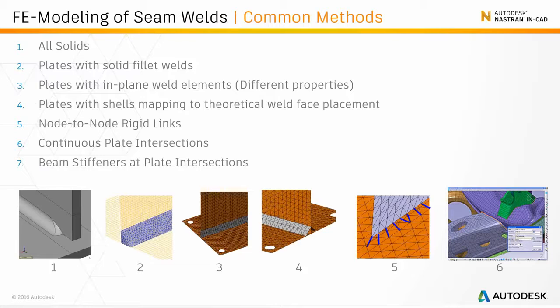So how should you model welds in finite element analysis? Well, there are lots and lots of ways that people model welds, including some of those listed above. Any one of these is going to give you decent load transfer, which is really what we're looking for, the transfer of load force between adjacent geometry. But that's about all you can expect. Some of the more preferable ones that you see here are most likely going to be items 3 to 6. The reason for maybe staying away from the likes of number 2 is that